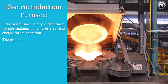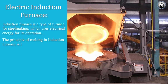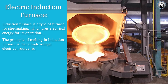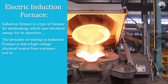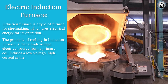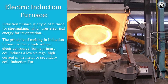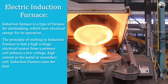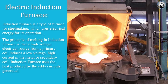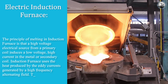The principle of melting in an induction furnace is that a high voltage electrical source from a primary coil induces a low voltage, high current in the metal or secondary coil. Induction furnace uses the heat produced by the eddy currents generated by a high frequency alternating field.